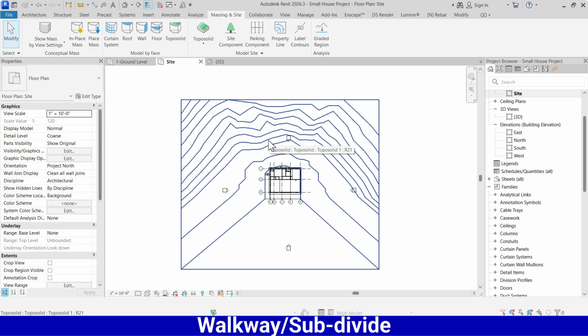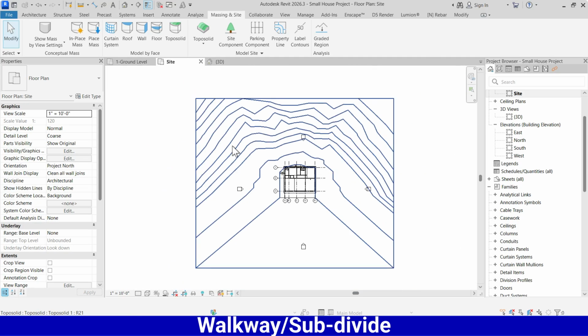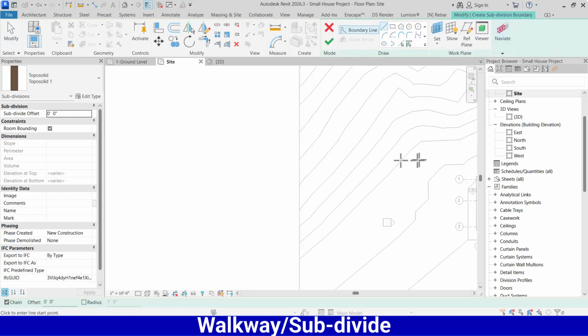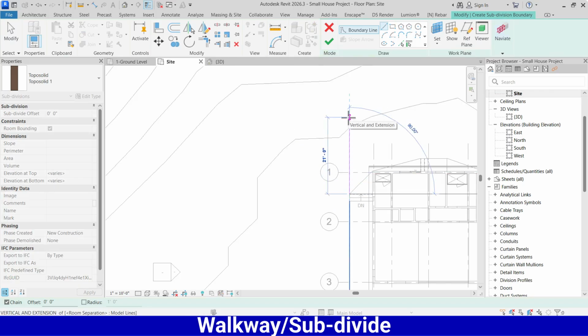That's so simple. Now I want to make a path here. To create a path, select the Toposolid, and then from here select subdivide and draw as per your requirement. I will draw maybe like this.